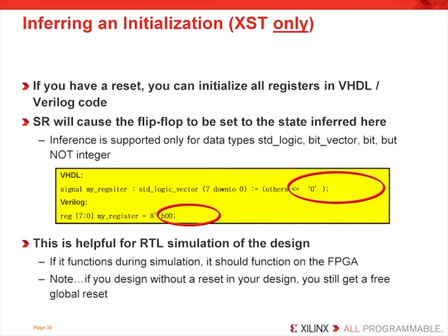Now please note that what this means is that by using an FPGA, you get a free reset because the GSR is activated after configuration by default. If you want to control the reset state, you can with this example. This can be helpful if your design does not use any local resets. And as we shall see, if we remove the global resets from our design, we have an easier time getting the dedicated hardware inferred. You could still use a reset in your design if you wanted, but we might not bother in that case. And remember, if it simulates properly, it will function in your FPGA.